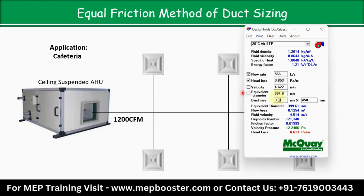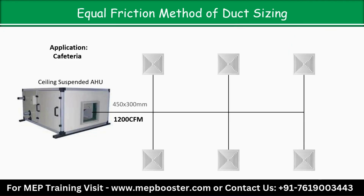Okay, so you have to select the height as per the space availability on site. Right now with 300 height, the width of the duct we have got is 450 for 1200 CFM supply air, correct? Here I have written 450 by 300; always write down the larger size first and then the shorter size. 450 is the width of the duct and 300 mm is the height.